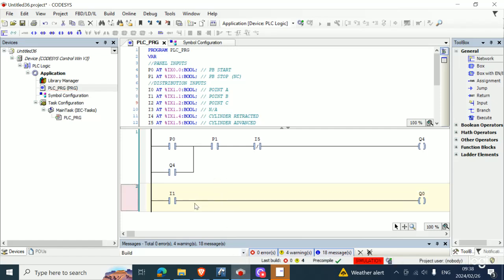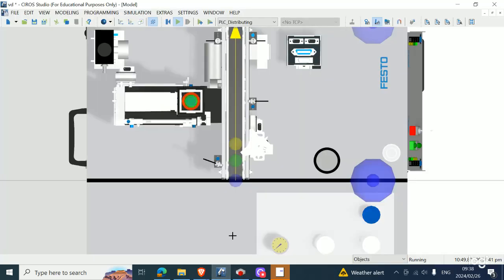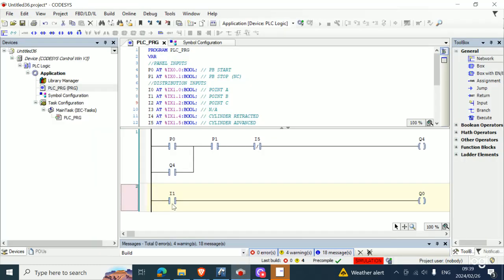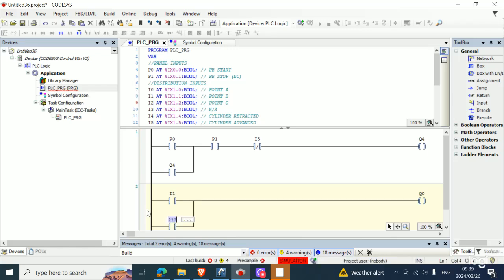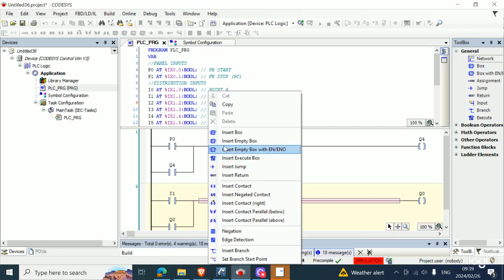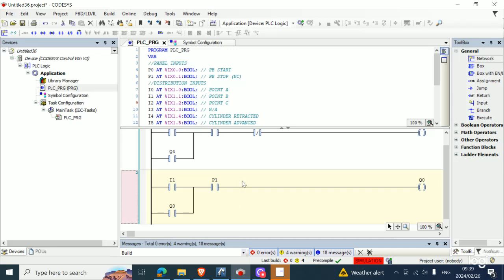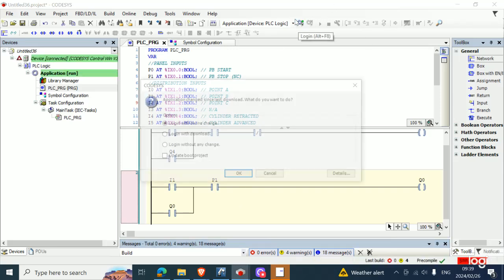And then to ensure that I1 sends a continuous signal to Q0, so Q0 can keep moving, because if, for instance, the part comes to here and then begins moving immediately after the sensor turns off, if you didn't latch this sensor, the conveyor will stop because the signal won't be there anymore. So now we have to latch our circuit here, which you want to latch by the output, and then you want to put in our P1 in case we need to stop the process. So now we're going to run our circuit again.